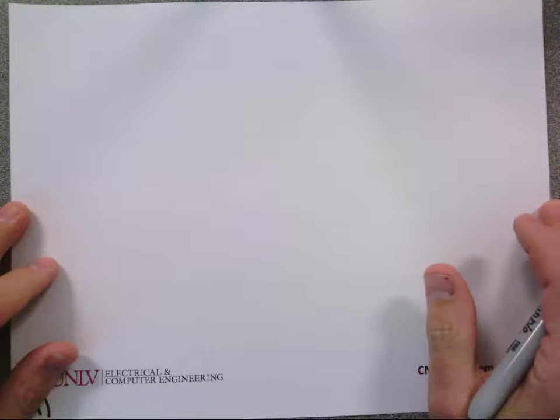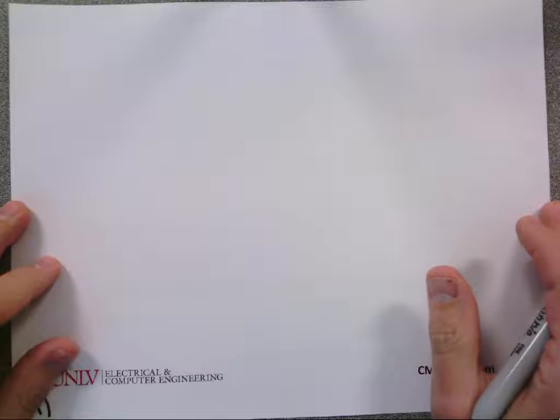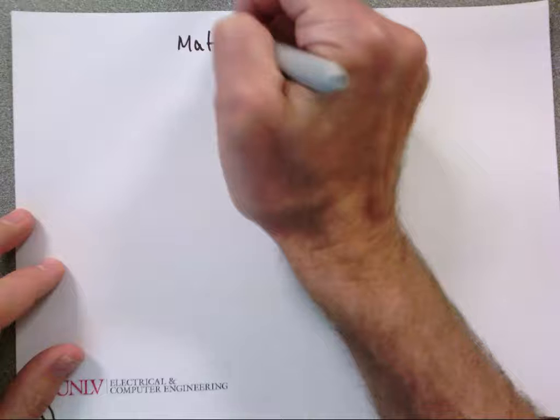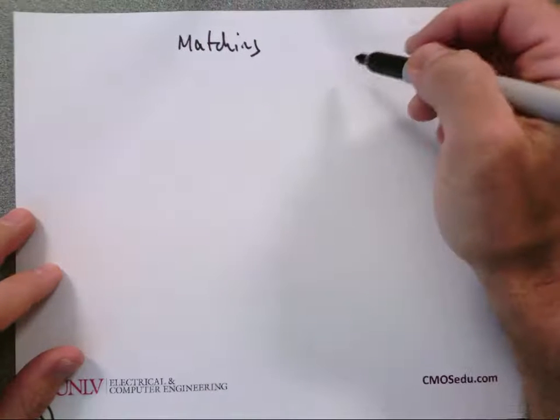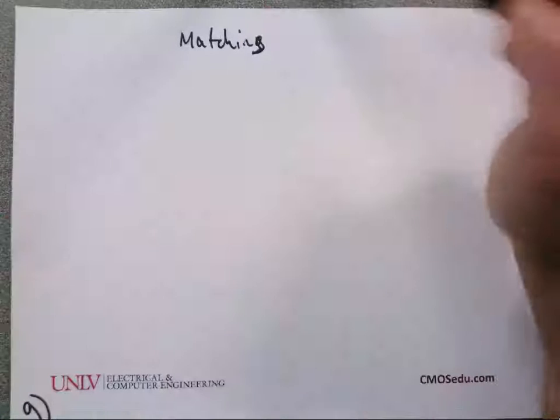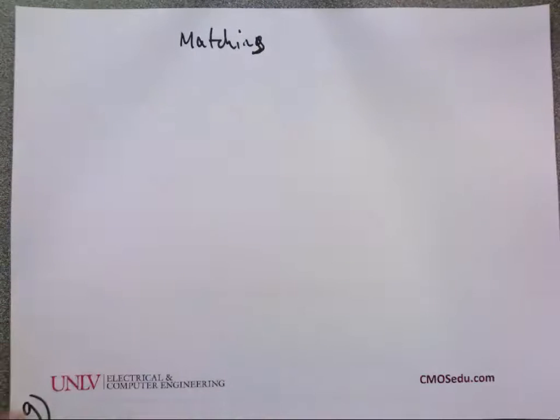In 20. What? How about matching? No, that's too much. You're testing this over too much material. What's the most critical thing for matching and why? Just one sec. No, you don't. VGSs are generated. They don't change. I mean, they're assumed to be the same. You change your VGS, you're not going to get good matching. It's a current mirror. They got to be the same.